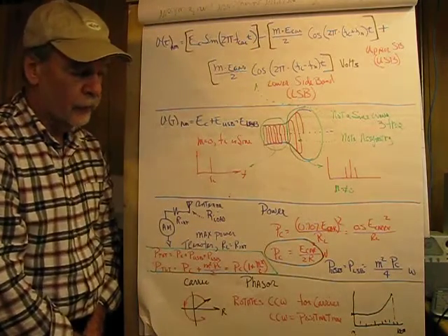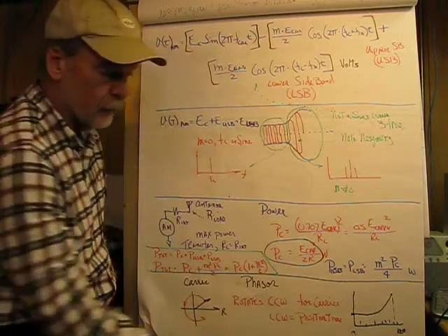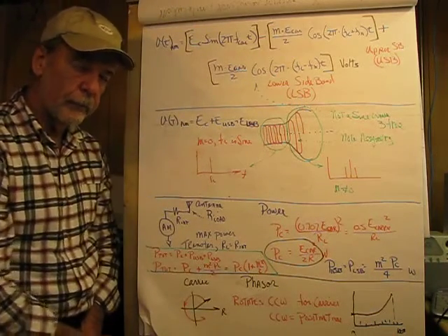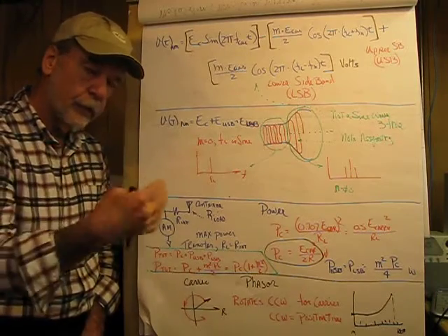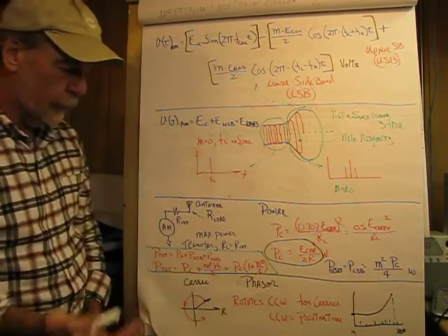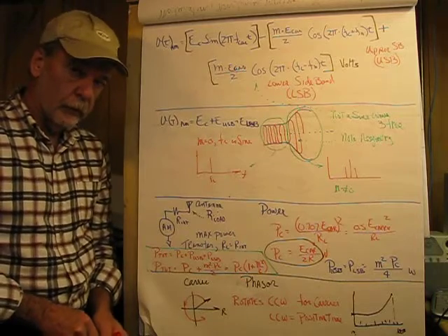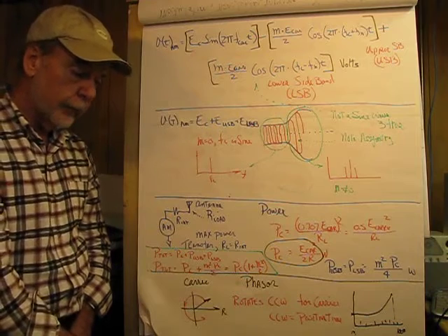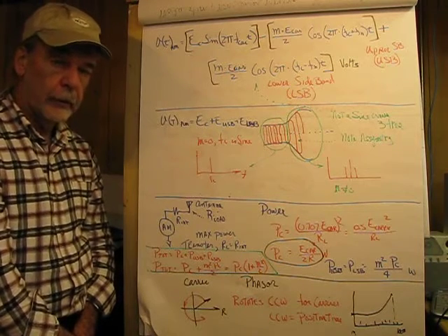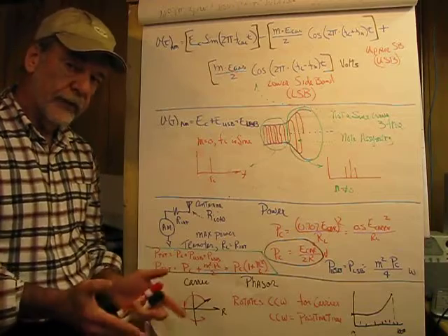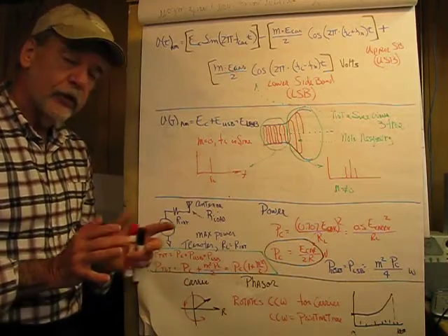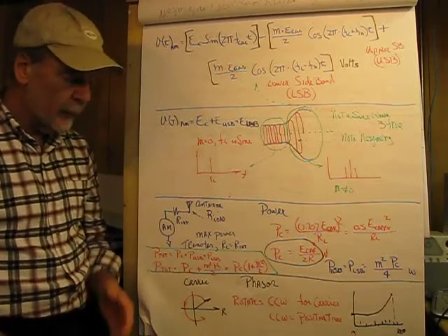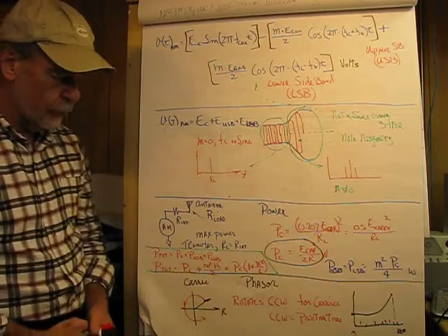Now, it's desirable to run a higher percentage of modulation because the power increases significantly as M increases, and that's the ability to reach further for a larger audience. For example, Cleveland transmitters try to pick up the Akron and Canton areas. Why waste power in Lake Erie? So they may have more than one tower to directionally send that into another metropolitan area. And all of this, of course, has to do with the approval of the FCC.